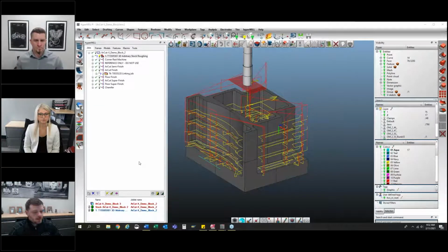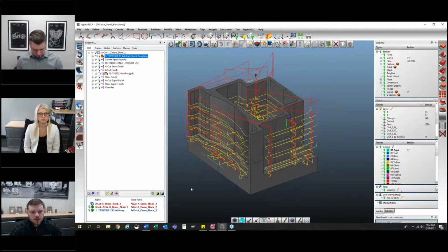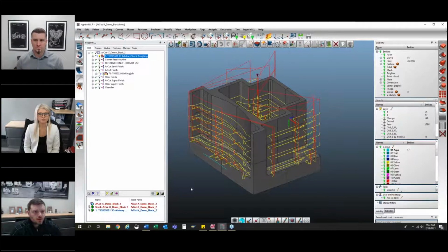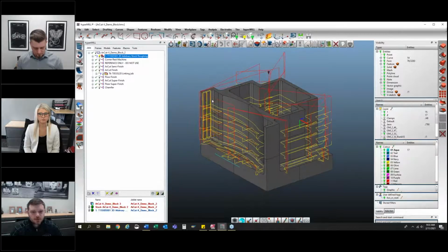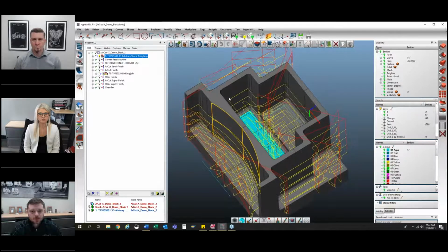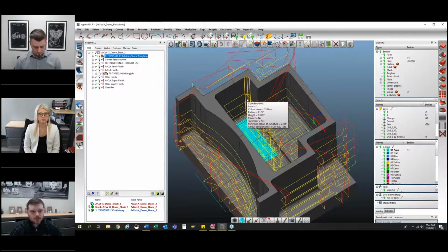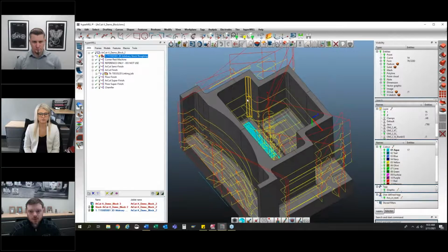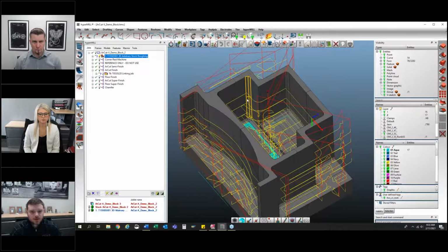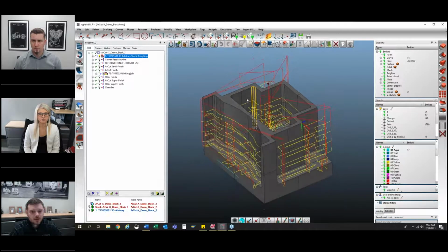Okay. So this part here is another aluminum part, except in the 6061 aluminum that we did. We chose to run this one all with our conical barrel tool that we call our R-Cut X. You'll see that it's relatively deep pockets with small corner radii. So in order to finish that, you'd need a smaller tool sticking out quite a ways. That's where the R-Cut really benefits.